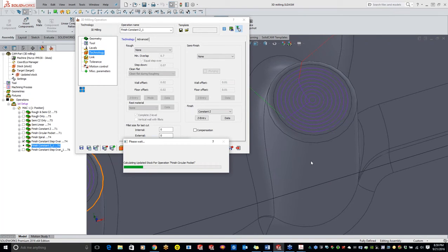Another one I was going to go over is the pencil milling. Pencil milling works great for, let's say, this surface right here and all these radiuses. You can tell it to do pencil milling, and you can tell it just a number of cuts. So maybe if you just want to do one cut going up a 3D angle surface, doing that radius at the bottom, you can limit it to one cut and just follow that ball all the way up a 3D surface. It's kind of like the HSS where you can determine the number of cuts, is another good way of putting it.